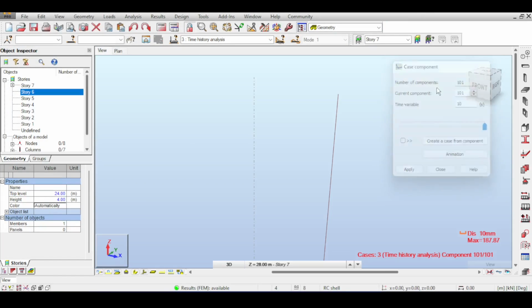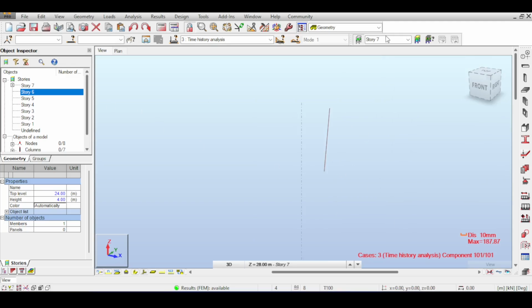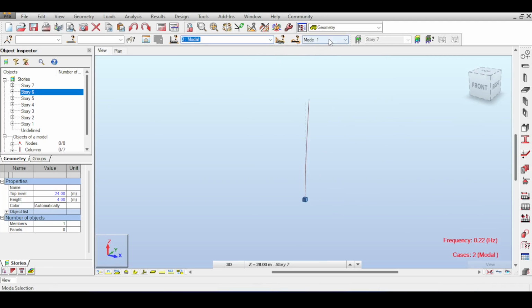So okay, let me rephrase what I have done here. I tried multiple times because it took me a lot of time. Just to remind you, my model analysis gave me the first mode in X at 0.44 hertz, meaning one vibration each 2.27 seconds. So now I've modified my time history to apply a pulse each 2.27 seconds. So let's take a look if it worked or not.